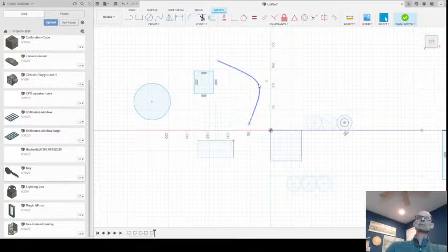And if you select something and then click construction, I just did that to this curved line here. You can see it becomes a dotted line. And these act and behave the same way as lines that you would create, or if I took this circle and clicked construction, you put them on the screen and then manipulate them the exact same way that we've been doing so far. But once you identify them as construction lines, they no longer have an active part in the manufacture of your objects. What they're there for is simply for guides.